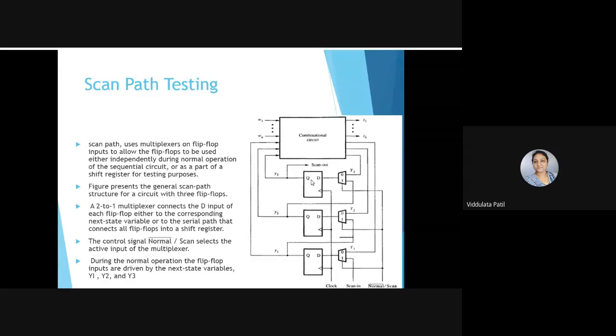not. Again we have another method, that is path sensitization. Okay, so in that what we are doing, we are giving input to only one of the input signals, that we are going to vary, and for the other input terminals, for each of the logic gates that is used in the circuit, we are keeping it in such a way that the output of that logic gate will not be dependent on the other inputs.